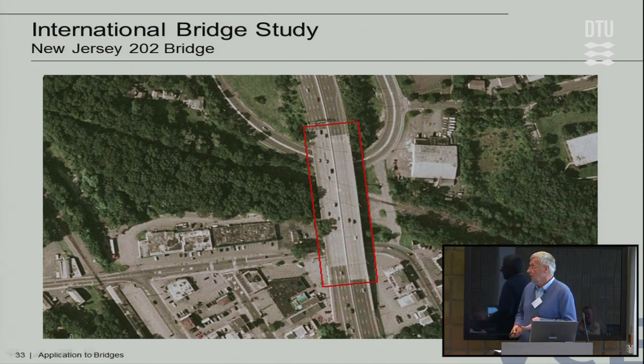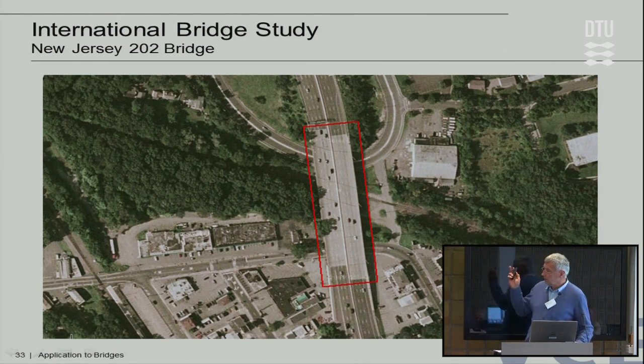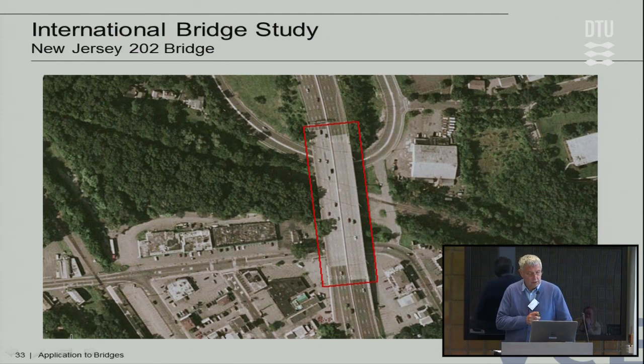So here we just would have been interested to see why a 5-time over-designed anchor broke. So to see a resonance in reality would have been fine. The same was with the video cameras, they also didn't work at that time. Only the tuned mass damper and the pylon worked, and we have a record of the tuned mass damper. Bad luck.